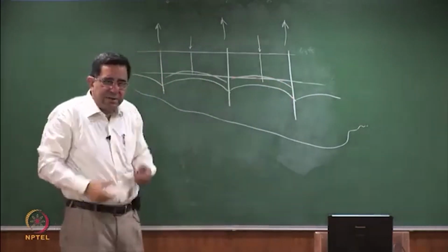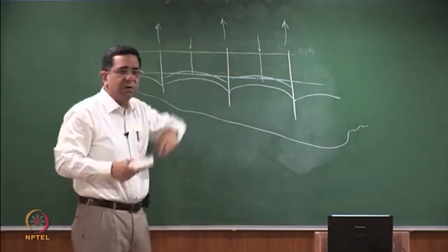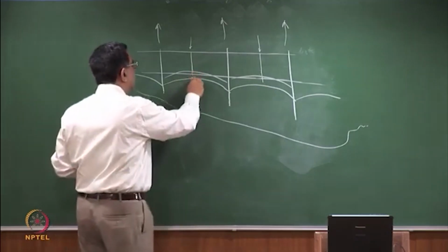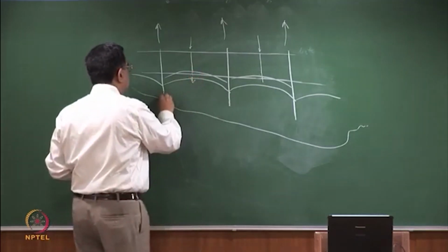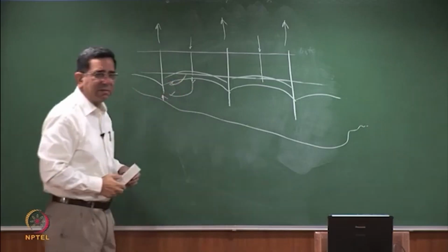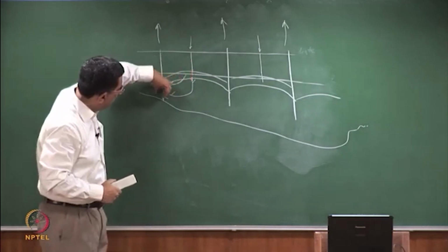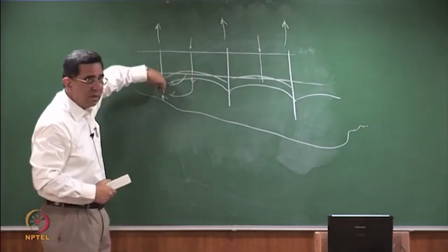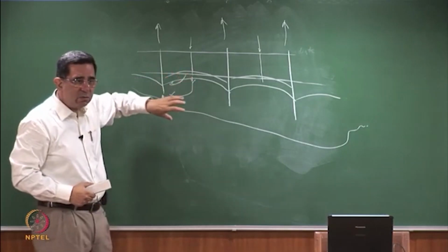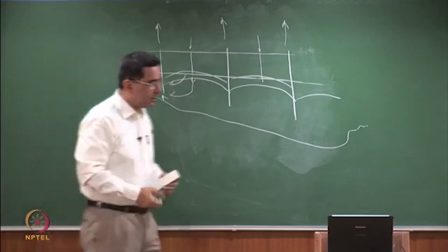So I have extraction wells which go to pump and treat. After treatment the water comes in, or in the beginning you are sending in fresh water. And remember, now you are sending in the water here and you are taking out the water from here. So there is in a sense flow taking place like this, right? So clean water is traveling from one well to the other. It's also washing the soil in between. So that is what is happening in your pump and treat.